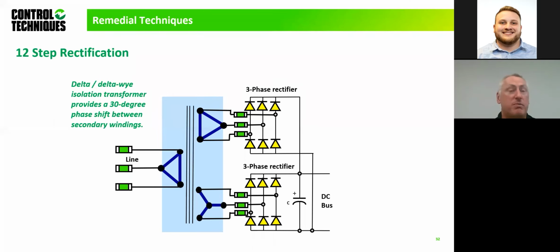They work really well, especially if they're on a common core, not separated. Nice balance of distribution of the currents. There are ways you can do this with auto-wound transformers. It's just trying to find that manufacturer at the right cost point to do that, but not to the same performance as an isolation or double wound transformer like shown on this diagram today.